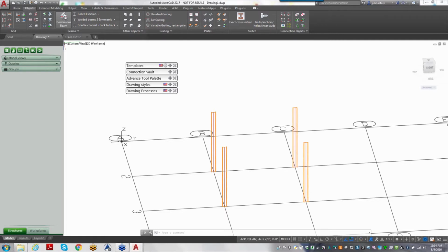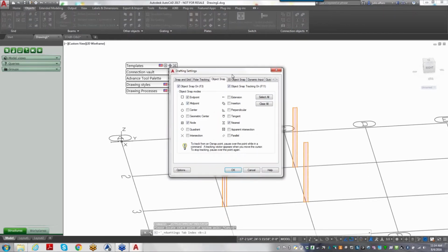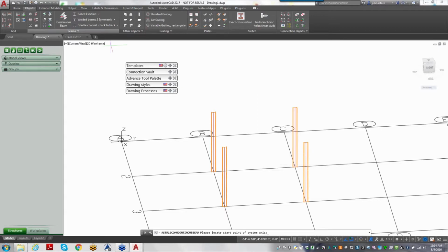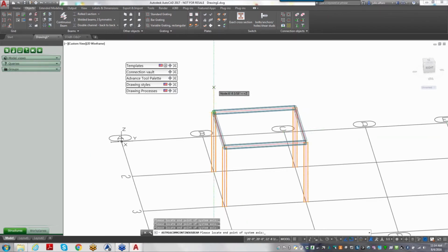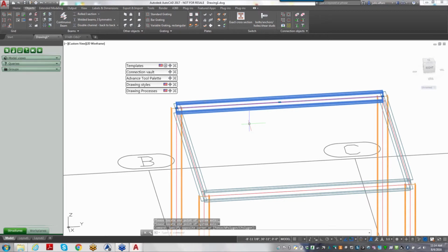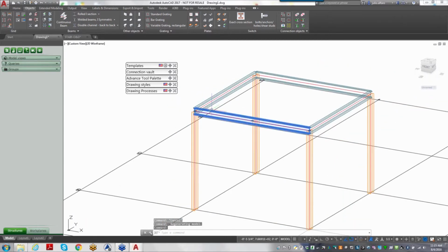The next thing we can do is create a beam, which is this right here. Now, to make it easier on myself, I want to snap to those axes that you see right there. So I'm going to clear out all these and just do the node. And then once I come in here, even at a distance, I can snap to those real easy. And notice it's a continuous beam. But when it gets created, it's individual beams. It's not one whole polyline. Some people confuse that continuous beam as a polyline. It's not. It's actually just letting you create the same beam throughout without stopping.